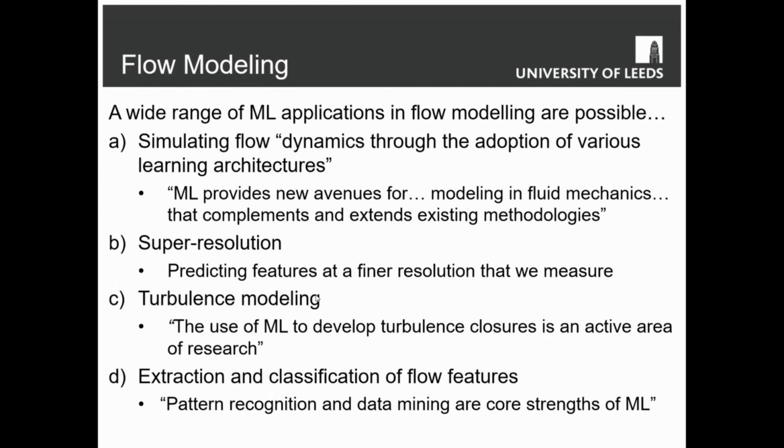The way he'll do that is to take as the input this coarse resolution flow and then use a neural network to try to simultaneously match the coarse grain resolution that's observed, but also satisfy the Navier-Stokes equations at a finer level, and do it very efficiently, not a full CFD solve. That gives a much finer resolution flow that matches the observations but also satisfies the underlying PDE model. That means that we believe it's a true representation of the flow. And then he'll be able to use that to calculate the wall shear stress and the other things he needs